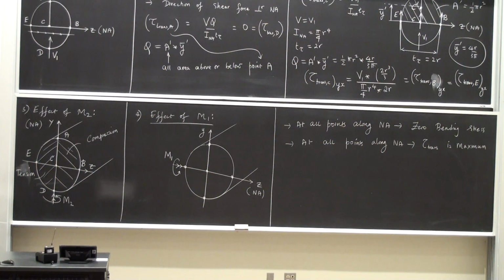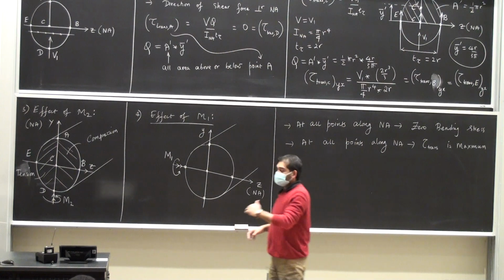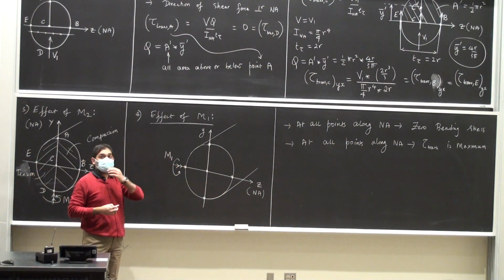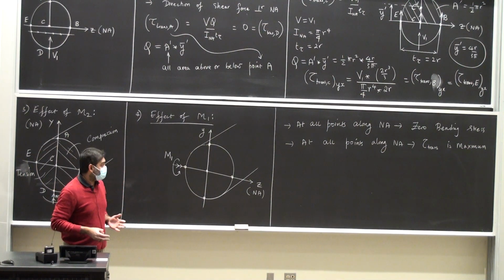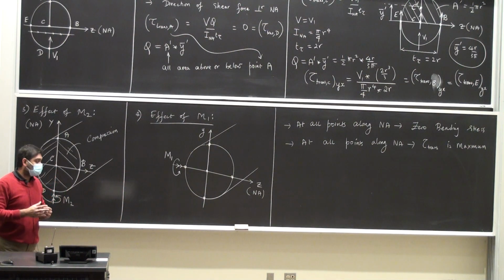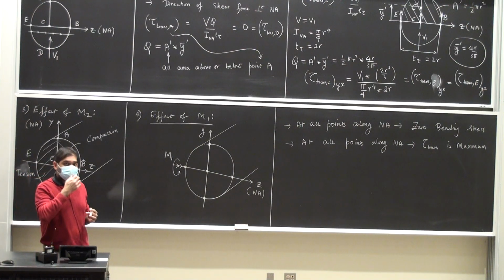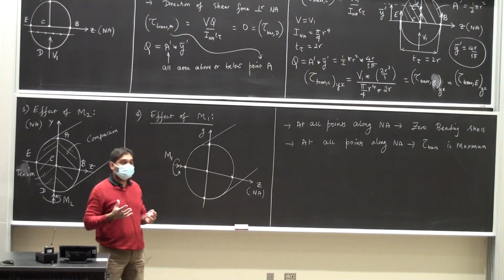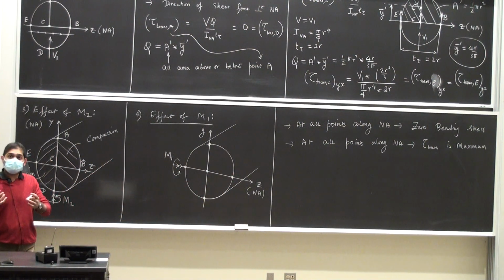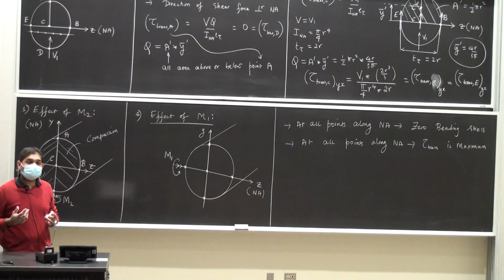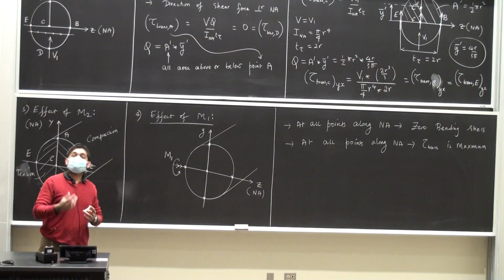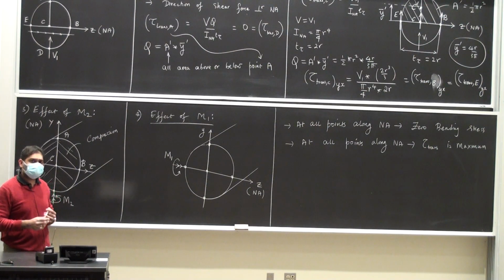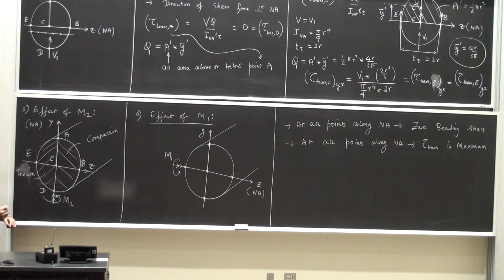The neutral axis is why it is a special axis. This is why you studied centroids in statics, and this is why you are studying moments of inertia in statics as well, so that you can use them to calculate the stresses. And one of the things that you do in manufacturing is you want to optimize this moment of inertia. You want to come up with a cross section that is the most optimum in terms of design, something lightweight, very efficient, which does not take up a lot of space or a lot of material. All of these stress calculations will go into the design considerations. If you're taking machine design or machine elements, you come across these next semester.